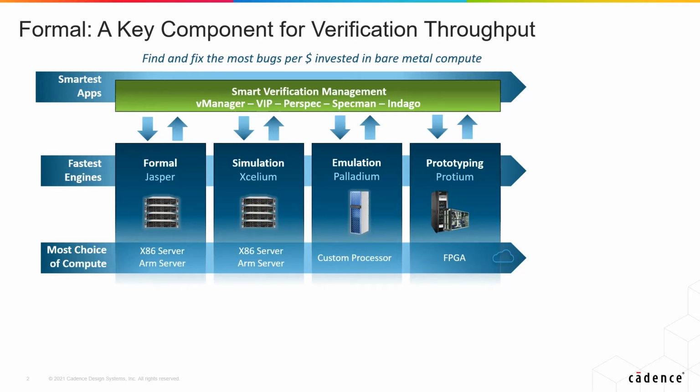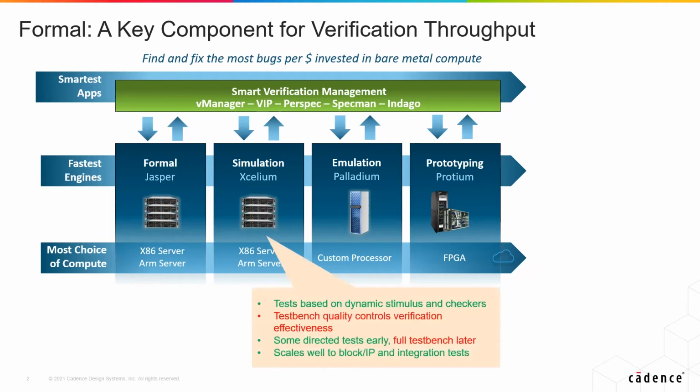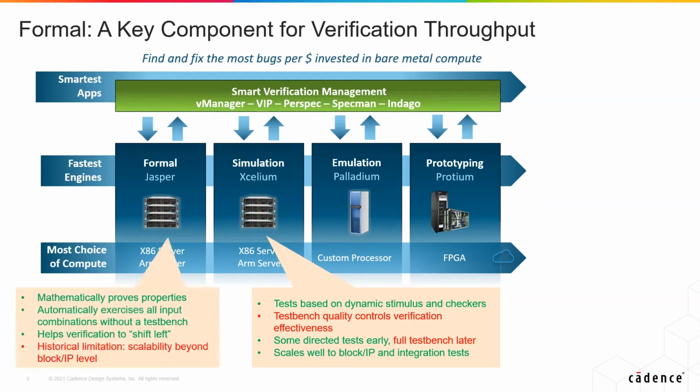But first, let's go a little deeper into simulation. The tests are based on dynamic stimulus and checkers. So really, it's the quality of the test bench that is controlling the overall verification effectiveness. Some directed tests can be run early, but in general, the verification engineer is developing quite a complex test bench, which will be complete later in the process. The advantage of simulation is it scales pretty well beyond block and IP level to full system integration tests.